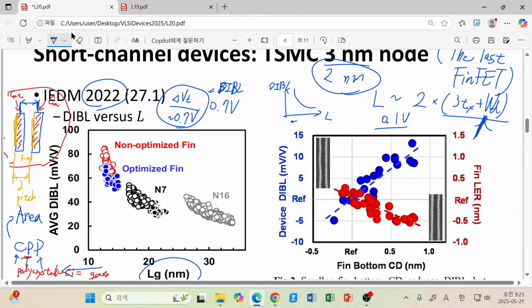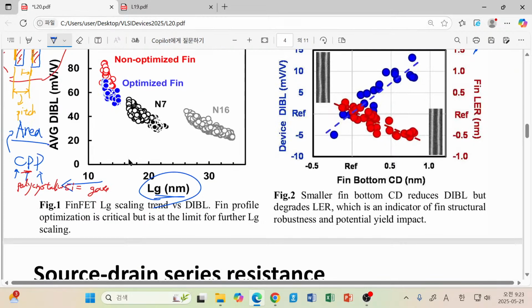They are placed in the same plane, and when we place them, the minimum distance between one transistor and another is given by this CPP value. So minimizing CPP is directly related to the reduction of chip area, because the unit gate can be reduced in terms of area. That's the reason why we always wanted to reduce the channel length.